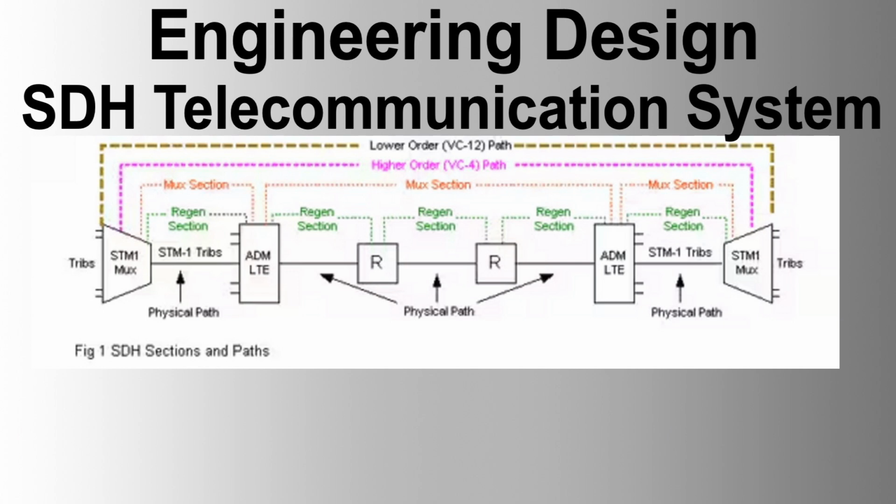Fiber optic telecommunication network philosophy. Backbone design. The fiber optic telecommunication network backbone design shall be based on distances to be covered across the pipeline, the type and criticality of systems to be interfaced with, as well as bandwidth, availability, and reliability requirements. The fiber optic telecommunication networks shall be based on a sequential network topology with redundant direct transmission paths.